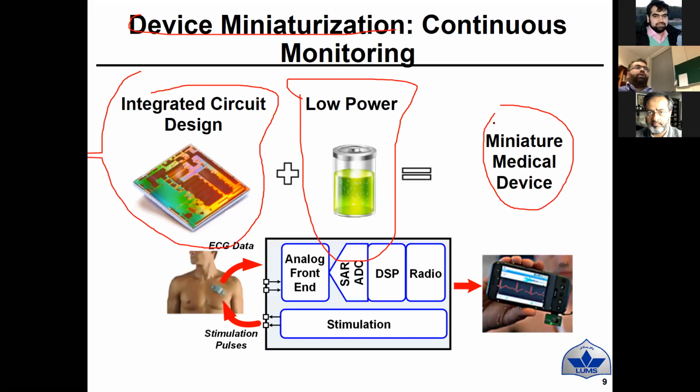So we have worked on this ECG device, which is like a patch sensor. Now we are working on a modified version of these things. It's going to have an analog front end, meaning it's going to acquire the analog signal, as real-time signals are analog. Then we want to digitize, and the best way to process at this moment is in the digital domain. Now even analog processing is bringing a lot of interest because of machine learning and deep learning.